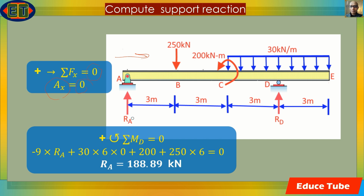So we will compute Ra by summing moments of forces about support D. Here, anti-clockwise moment I considered positive.